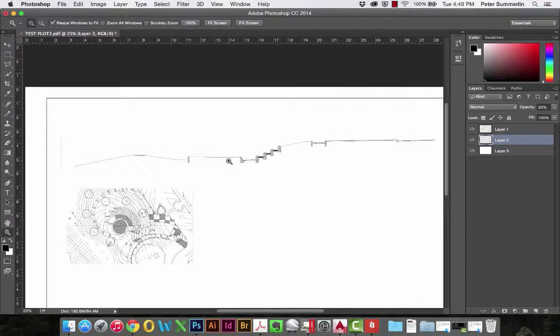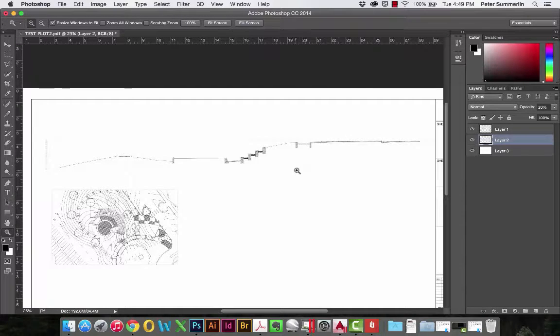Alright, so this is the conclusion of this tutorial. It essentially gets you from your existing grading plan to start creating that section line, right, and access with it using these guidelines. Now each section cut is going to be different, so there might be different steps to this process, whether it's using spot elevations to figure out where your next point needs to be, or just simply pulling guidelines up and wherever they intersect with that corresponding elevation. That's where you draw a line across.